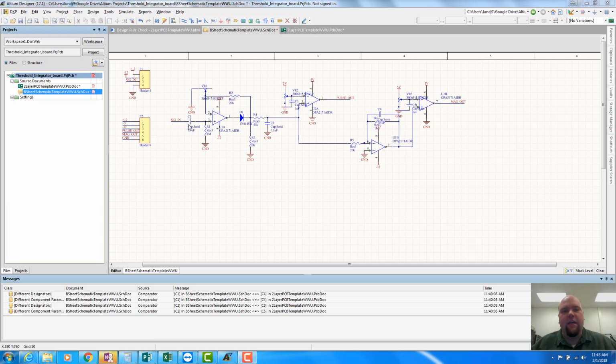So the signal is coming in. It is capacitively coupled here, which is going to remove any DC that might still be there. There shouldn't be any DC, but it'll remove any little bit of DC that's there. Then it amplifies it a little bit, an adjustable amplification. It halfway rectifies that signal, so now we should only have a greater than 0 signal after this. Then it runs that halfway rectified signal through a simple low-pass filter. This simple R4C2 is a simple low-pass filter.